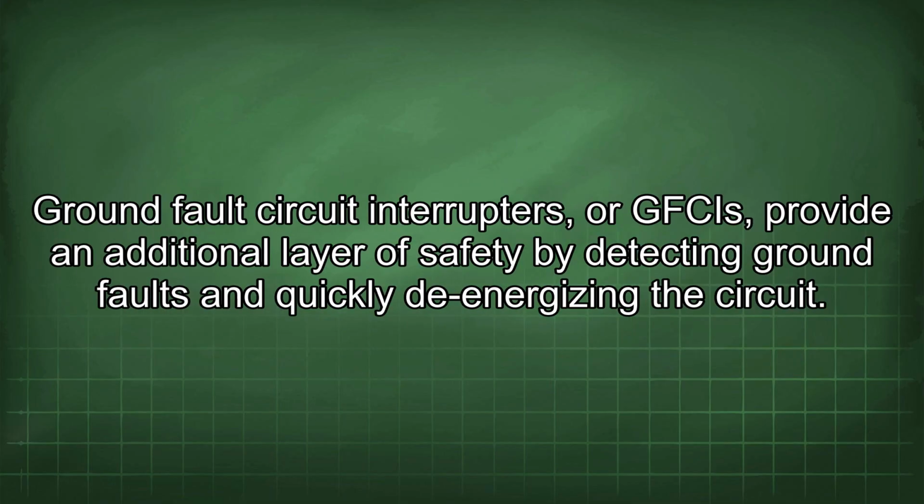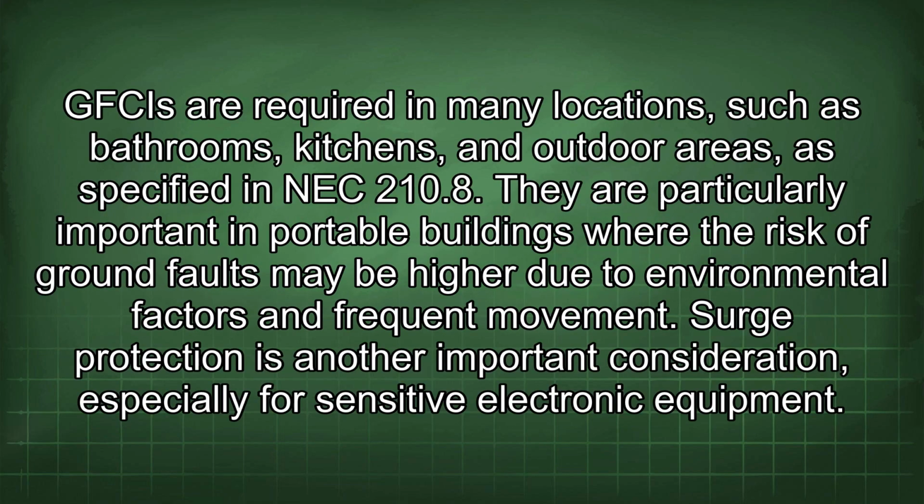Ground fault circuit interrupters, or GFCIs, provide an additional layer of safety by detecting ground faults and quickly de-energizing the circuit. GFCIs are required in many locations, such as bathrooms, kitchens, and outdoor areas, as specified in NEC 210.8.